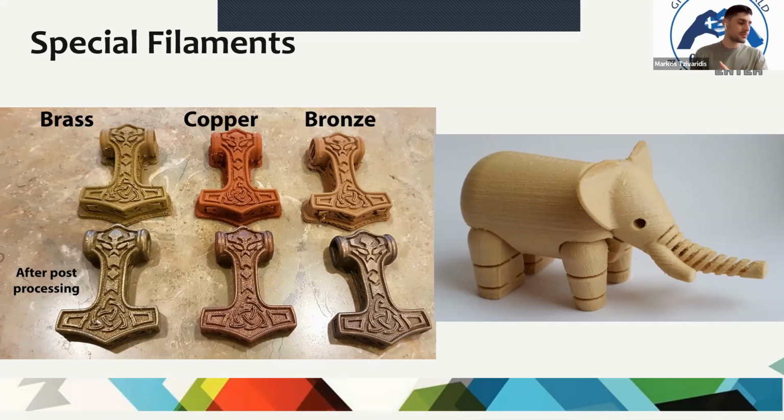It's PLA based. So the other 20% is more or less PLA. And it is easy to polish and post-process. When the print is done, it looks like clay, like the one here, but then you can use some techniques to bring it to that metal gloss you can see here. You can use a rotary tumbler to finish the part, or you can use some fine grit sandpaper and polish the print to the desired finish. So the better you polish, of course, the better the shine.